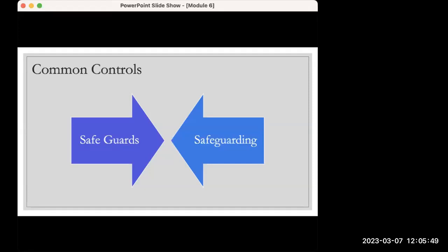Guards refers to a specific type of safeguard. Guards are physical barriers or covers that are designed, constructed, and installed over moving parts to prevent any contact with them by a person. Guards are the simple solution for protecting workers when access to moving parts such as belts and drivetrains is not required during operation. Guards are reliable, cost-effective, and low maintenance when properly designed and installed.